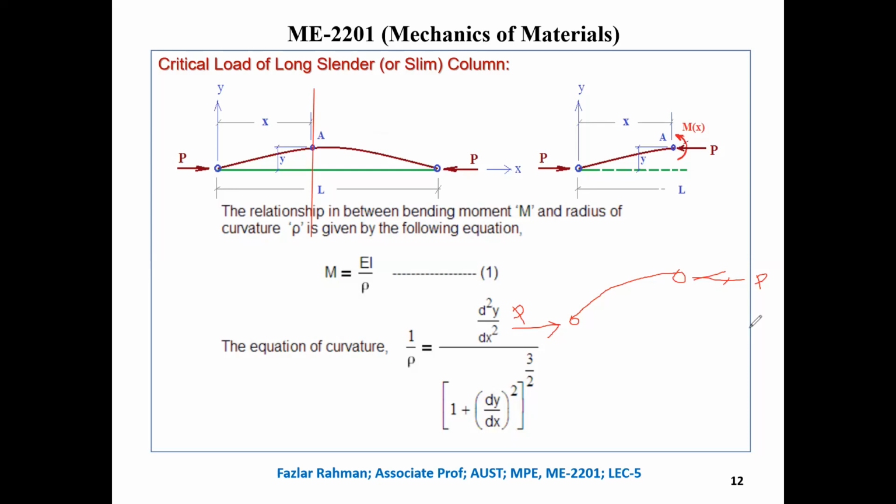Because, sir, there is shear force and bending moment. No shear force, but bending moment. What is your ID? Sir, 106. Okay, good. You answered two questions. There is a bending moment. Shear force works parallel to the cross section, so there is no shear force. This force P works perpendicular to the cross section.